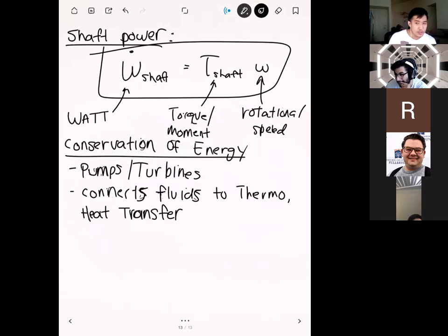But let's bring this back to fluids. Just like we always do with these kinds of problems, we're going to start again with RTT. With RTT, our first step is to define what our big B variable is, our extensive variable, and what our little b is. So let's start with big B. Big B in energy will be our total amount of energy, so it will be E total. Actually, let me give myself a little bit more room because E total is a little bit big.